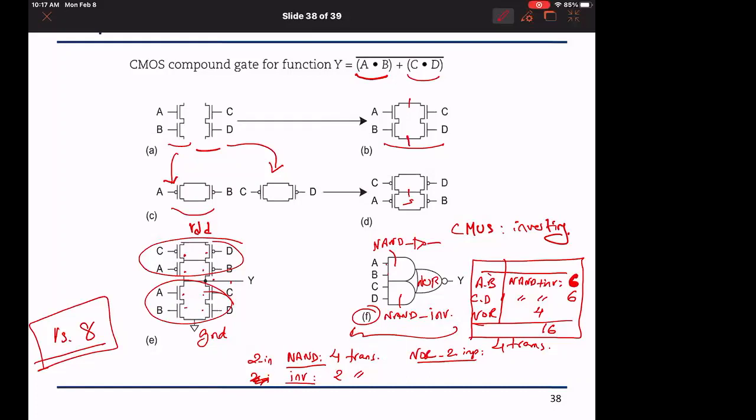We cannot keep going up in the number of inputs, but sometimes if we prove that the design implementation is compact and there is no delay penalty, for custom design, we tend to go with these specially designed gates, whereas we can go with the traditional basic gates or what we call library gates. And I can tell you that we can build any function from NAND, because I can use the NAND to make an inverter, I can use it to make an AND, I can use multiple NANDs to make an OR function, and so on and so forth.